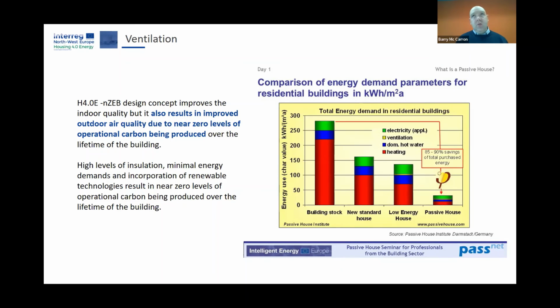Another thing worth highlighting is that under the passive house banner, there are actually 5 standards, and there's one that I think is particularly relevant to the Irish market, which might help with the quality assurance as well. The Passive House Institute has a low energy building standard, which is just below passive house classic, as we call it. That means the air tightness standard you're aiming for is relaxed, and your 15 kilowatt hours is relaxed to 25 kilowatt hours.